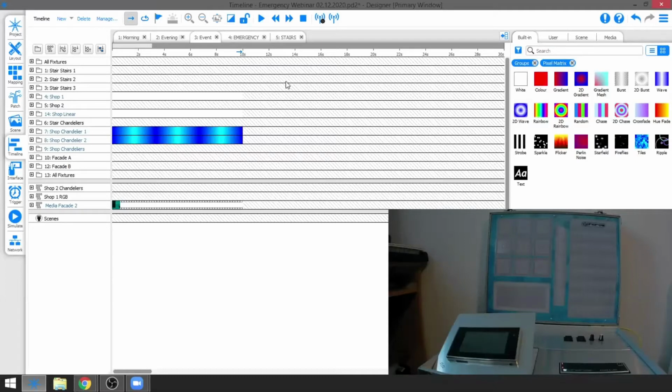Also, I should notice that timelines and lighting scenes within Pharos never release unless they are told to. So effectively what you create is a stack of timelines. If timeline 1 is selected, that goes to the top of the stack, and if timeline 2 is selected, that then goes to the top of the stack, and timeline 1 will slot in underneath it. That is obviously with the exception of priorities, which I've talked about already, which mitigate that latest takes precedence rule.